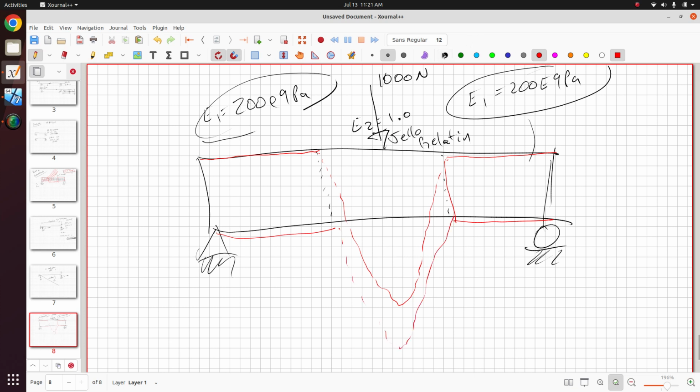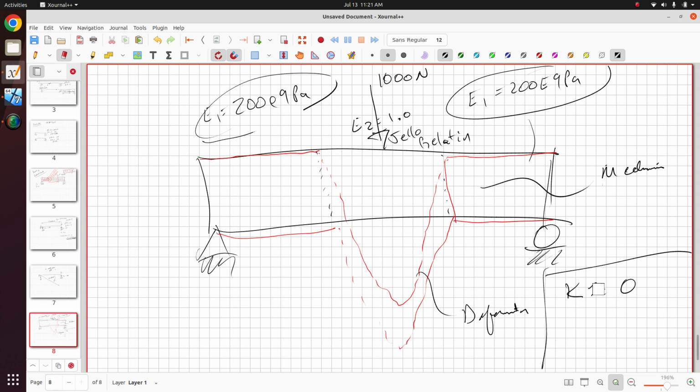So even though we do get some deformation, part of the structure is actually behaving as a mechanism. So this is another situation where if your stiffness here in the bottom right is close or equal to 0, that's going to cause another mechanism that's going to cause user fatal message 9050 in your F06 file.